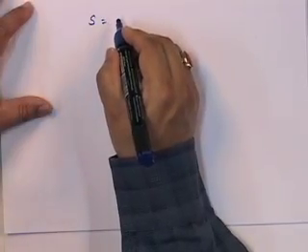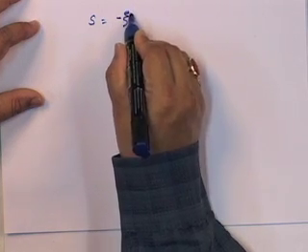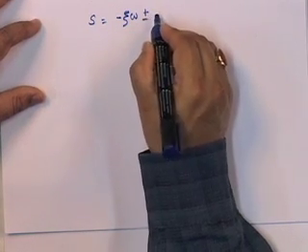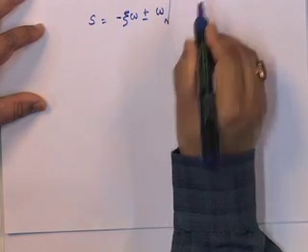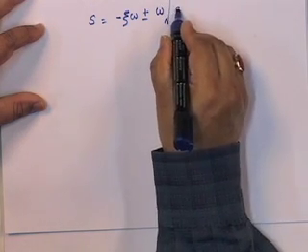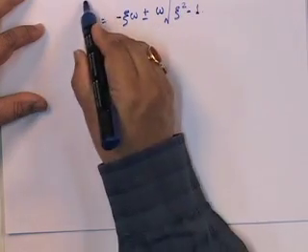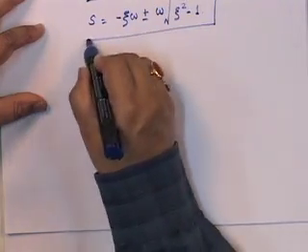Let us just go back to that solution and let us look at S is equal to, now C upon 2 m, minus C upon 2 m is minus xi omega plus minus, okay, omega is going to come outside, square root of xi squared minus 1. This is what that solution turns out being.